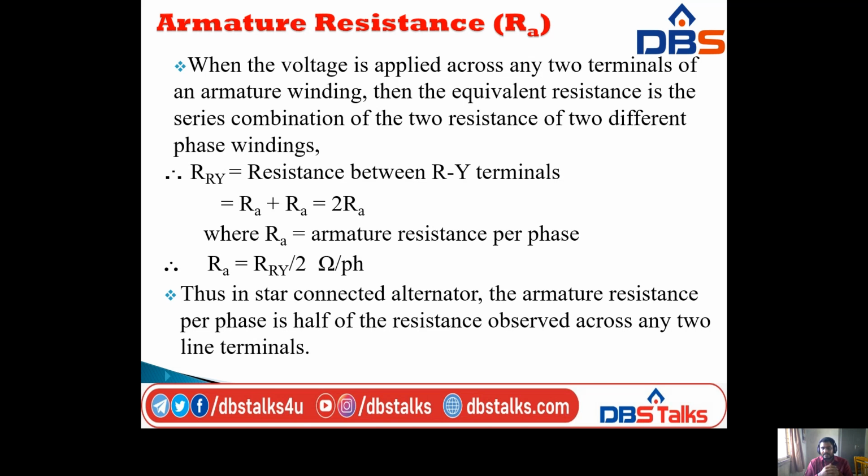In a star connected alternator, the armature resistance per phase is half of the resistance observed across any two line terminals, that is R_RY.